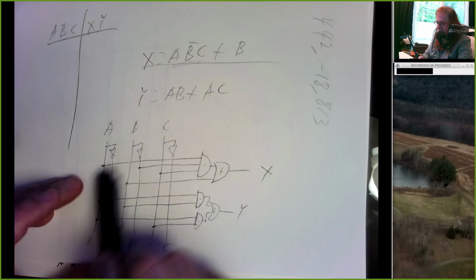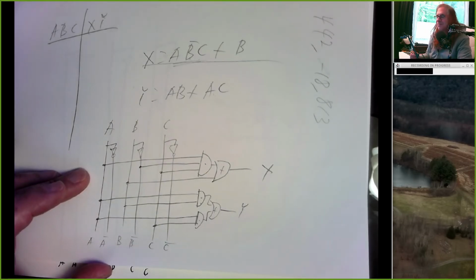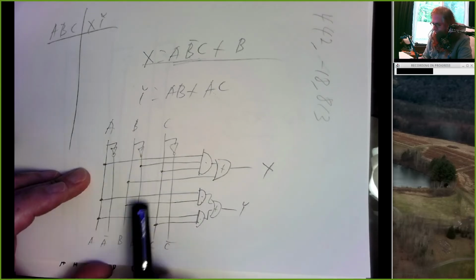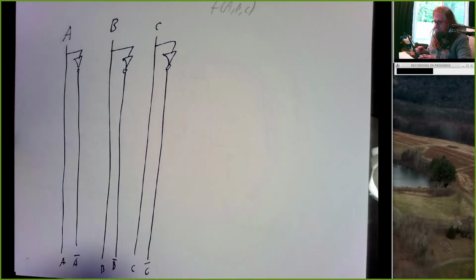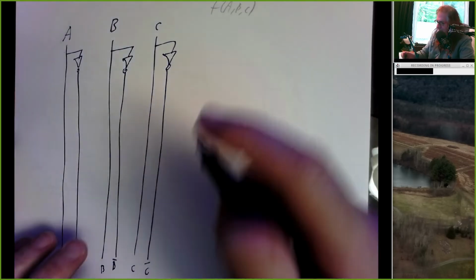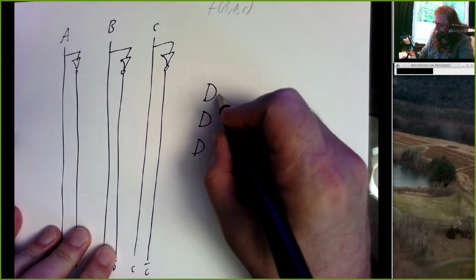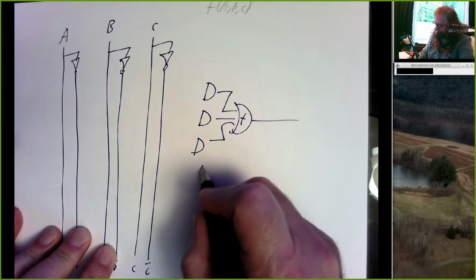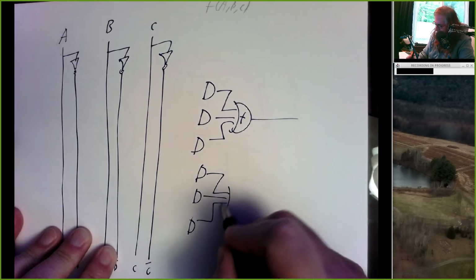And this left part of our circuit diagram is pretty much the same from one circuit to another. The place we put these connections changes, right? But we always have our inputs, we have our inverters, and then a bunch of AND gates, and maybe these get connected to an OR. And maybe we have some more AND gates, and these get connected to an OR.